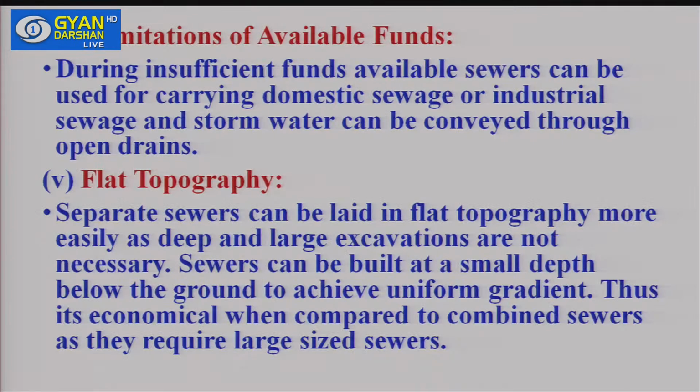Then next situation is limitation of available funds. If we do not have enough funds, then it is better to go for the separate system, because the combined system needs more cost, more finances. So if we have a lack of funds, then it is better to design a separate sewerage system.